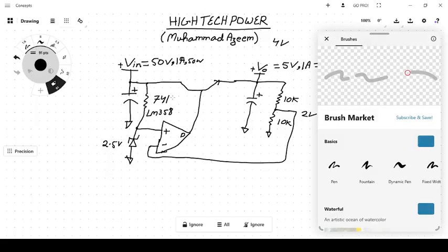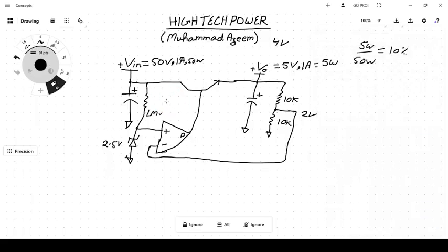So we'll delete the op amp numbers from here and go back to the same circuitry. However, now suppose it is a comparator. The pinouts of the normally available comparators and the op amps are the same, and their symbol is also the same.